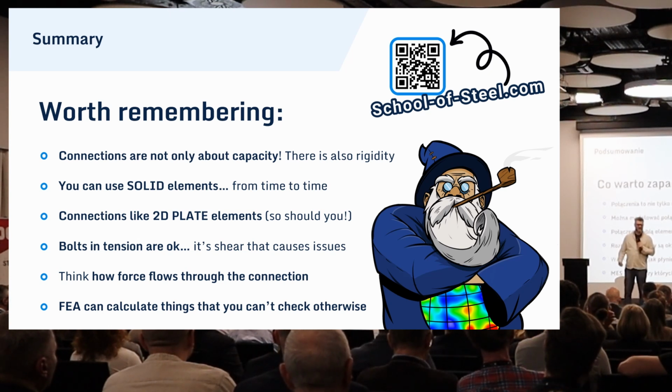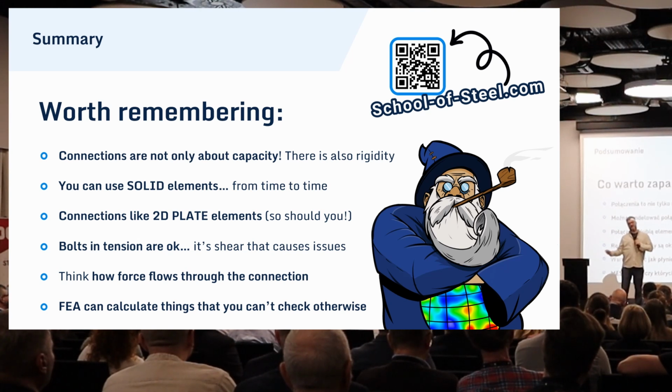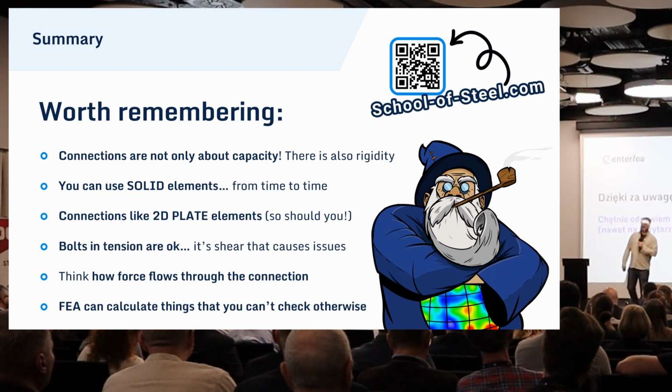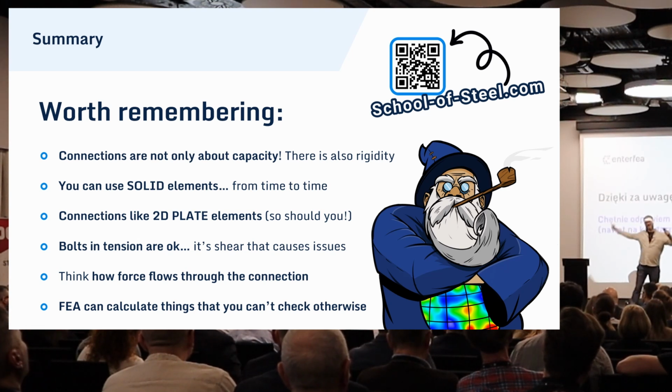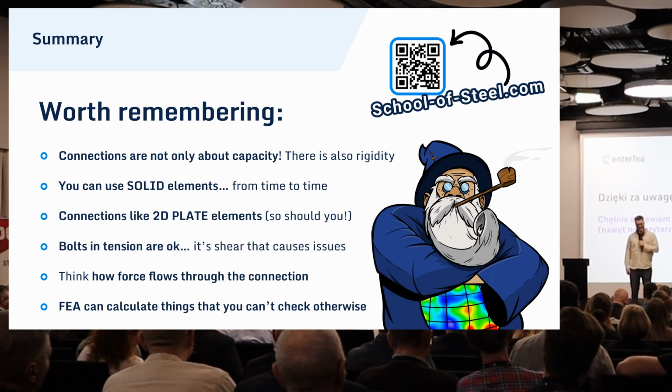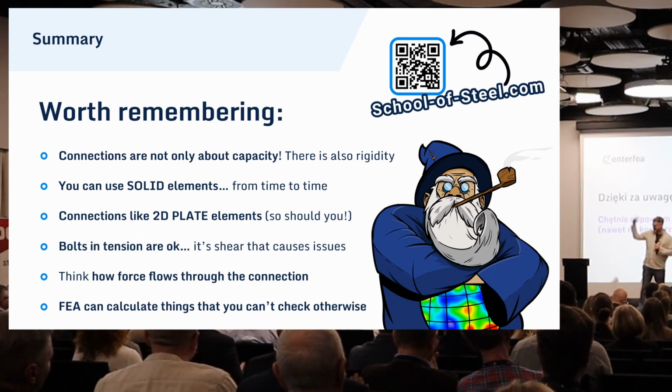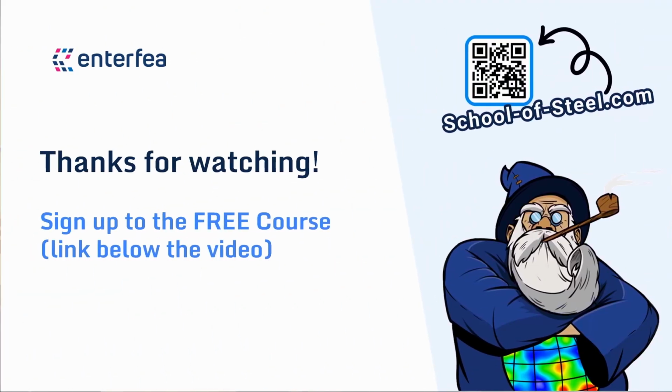And I definitely do not want to convince you to use FEA to calculate every connection. That's absolutely not the case. But when you are in need to calculate something and code simply does not allow you to do so, using FEA to calculate the capacity of such connections is a godsend, because FEA can literally calculate things that you wouldn't be able to otherwise.